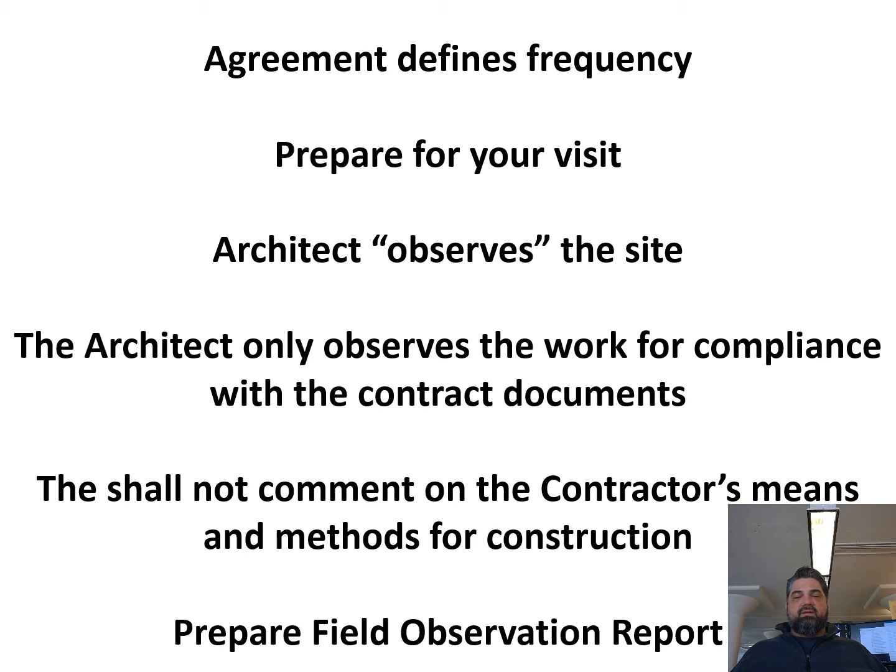The point of this sentence is that the contractor is responsible for the means and methods in which all of that work takes place on site. You never want to say, hey, I don't know why you're installing this now, it needs to be installed later after this stuff. Look, they're responsible for the means and methods. If you make a comment like that, either verbally out on site or in your field report, you open yourself up for all kinds of liability if something goes wrong and they say, well, the architect said to do it like this, install it in this manner. Well, you don't want that responsibility, trust me.